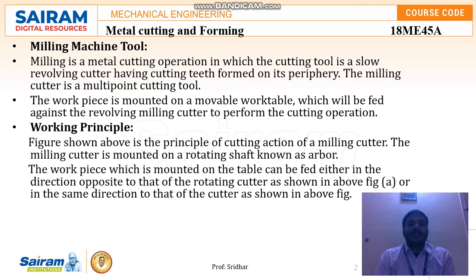The main functions of milling machines are gear teeth cutting, keyways, and slot making. This is very difficult in other machines. That is one of the major advantages and reasons why the milling machine is used in industries: to make slots or keyholes in very hard materials like carbide, tungsten, or cast iron, which are used as workpieces.